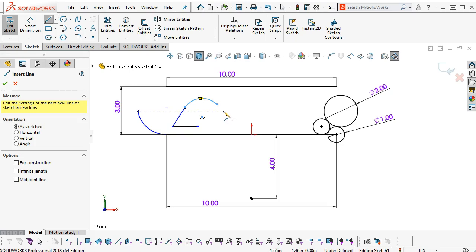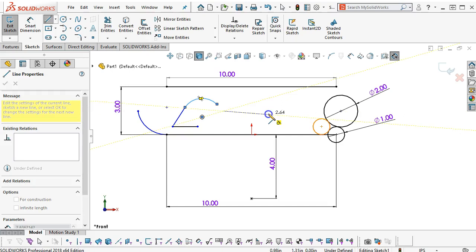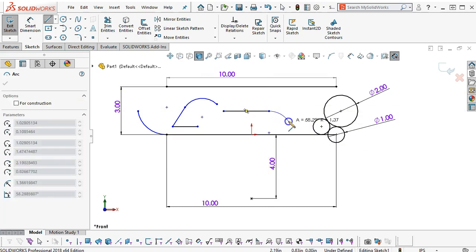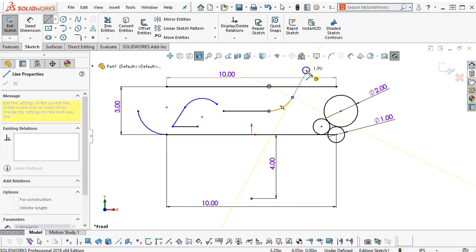So the 2 methods then: I am a click dragger, so click, hold down the left button and drag, and when you let go, you're pretty much through with that line segment, but you're still in the line command and you're ready to go back and pick up an inferred relation and start the next line command. So this is that continuous arc: before I let go of that line, if I come back to the start, I'm going to go right into a tangent arc and then right back into the line. That can be a very quick workflow if I'm generating a lot of geometry.